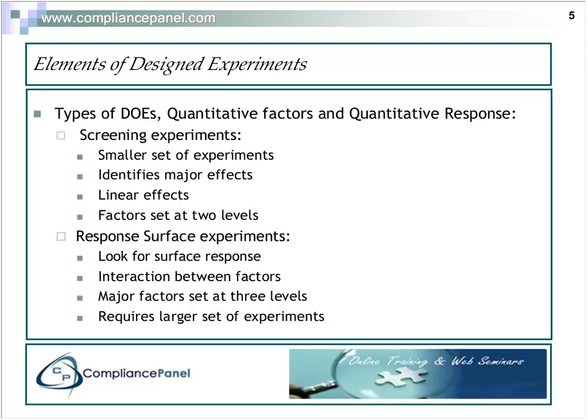Now, understand something about design of experiments. The response, the thing that we're going to measure, could be a quantitative number, so it could be the peel strength of that pouch, or it could be a qualitative thing such as pass or fail. And we're not going to talk a lot about what happens when your response is qualitative. What we want to concentrate on today, because it is an introduction, is when our response is quantitative. So we want to deal with quantitative responses and quantitative factors.